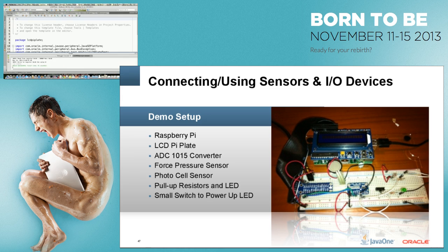The point is you now take buttons, which would typically be on a GPIO. Again, that expander I was talking about on the bottom is abstracted. You're not really talking to the Pi's GPIO, you're talking to the expander's GPIO for those buttons. We abstracted all of the calls, but it's the exact same: you set the input or the output of the GPIO, and you can get the values from it. Cool, so that's that one.